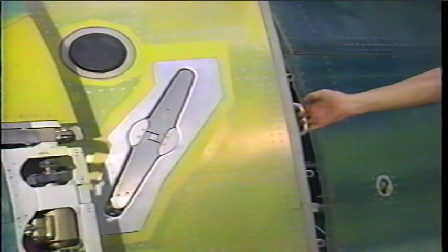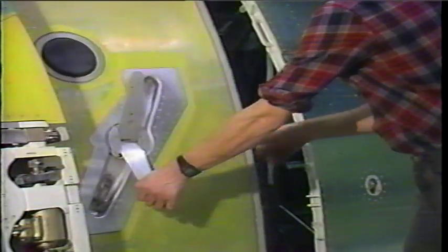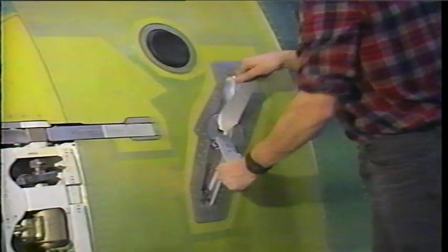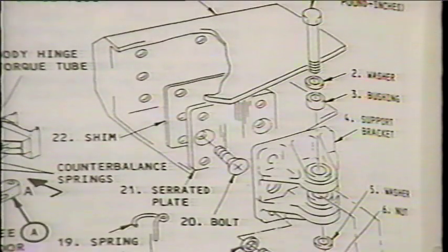The exterior handles should rotate 180 degrees and retract when the roller bearing aligns with the slots in the basket cam. If the handles rotate less than 180 degrees, move the guide arm support bracket forward on the serrated plate. This will increase the door torque tube and door handle rotation. If the support bracket is moved, check the guide arm again for preload.